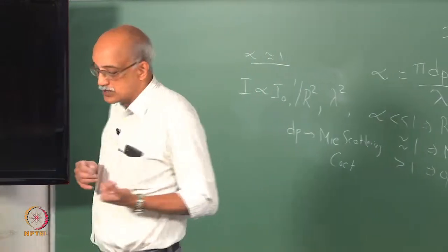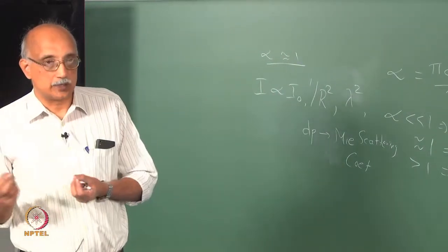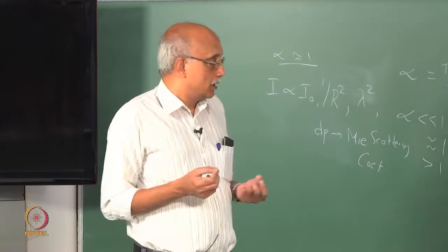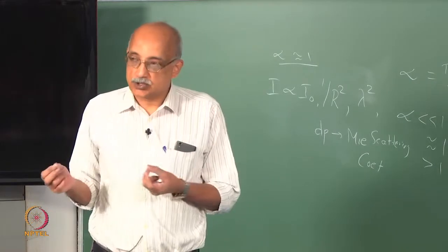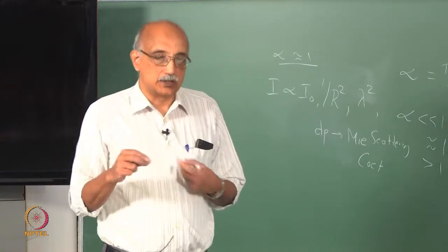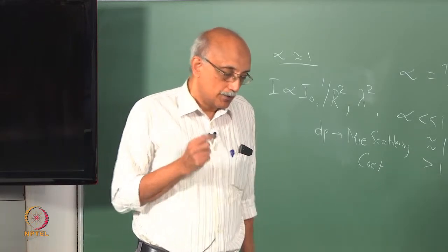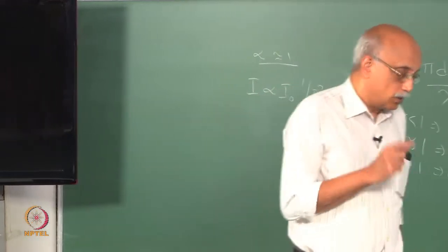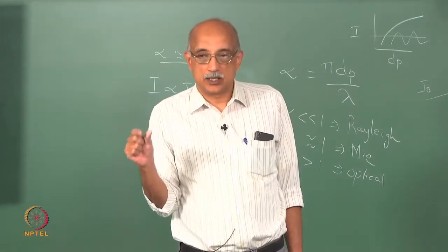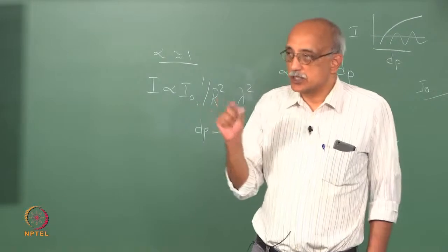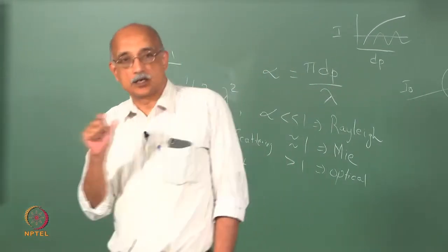S stands for sensitivity. Sensitivity is a measure of the smallest size a particle counter can measure. The next one, R, is resolution, which is different from sensitivity. Resolution, I think we talked about this in one of the earlier lectures. Resolution is a measure of how close can two particles be and still be identified as being two discrete particles rather than a single agglomerate.